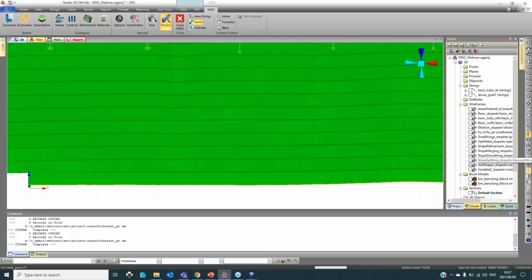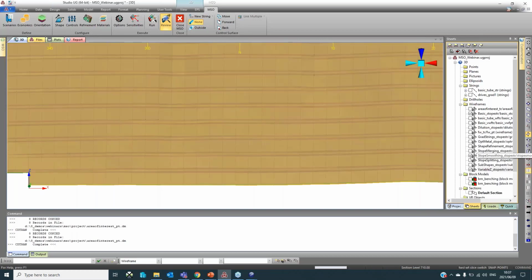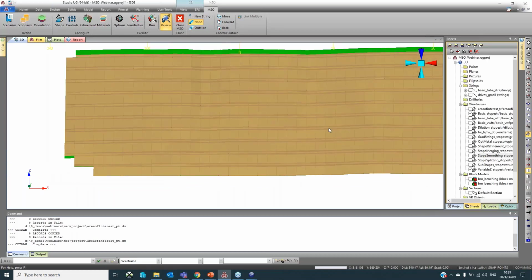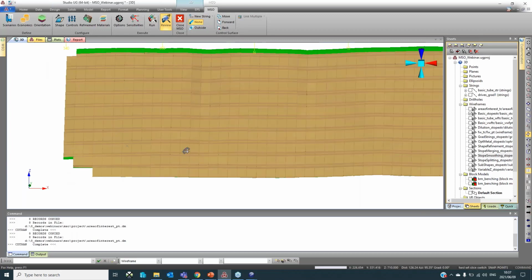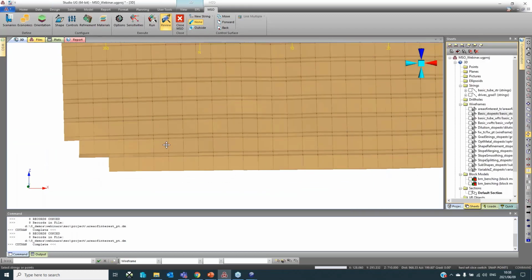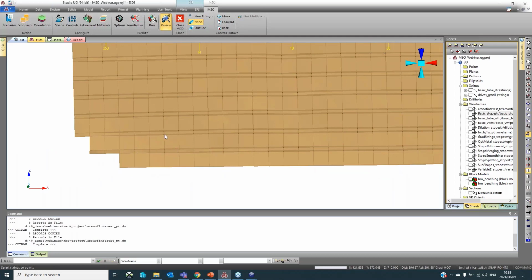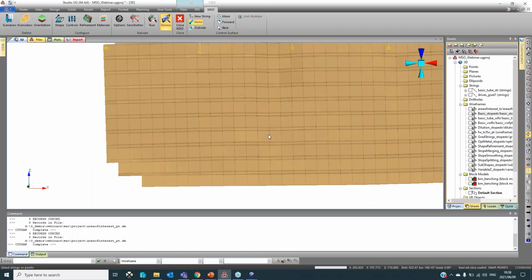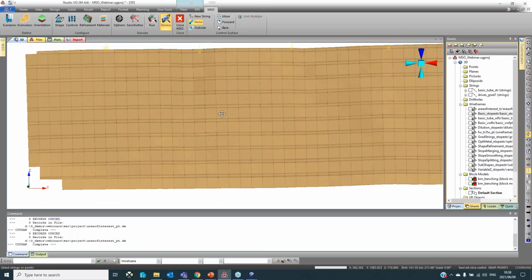And then the not the last one, almost the last one. We have this one, the variable z, so we can use that variable coordinates, the v dimension, to set up pillars between stopes. Like in this example, I use 5-meter pillars between panels. So I have a 10-meter stope, 5-meter pillar, 20-meter stope, 5-meter pillar, and then we can already know where they will be inserted. For example, with the output custom fields from the beginning, we can set a formula that if my stope height is 20, it's a stope. If the shape height is 5, it's a pillar. And then they are already identified by the end of your process.